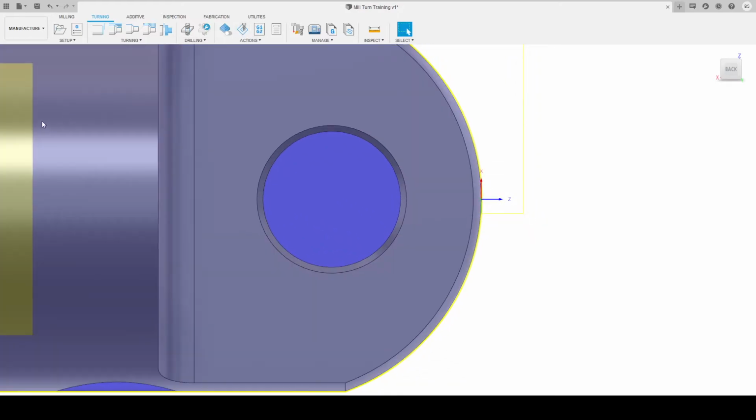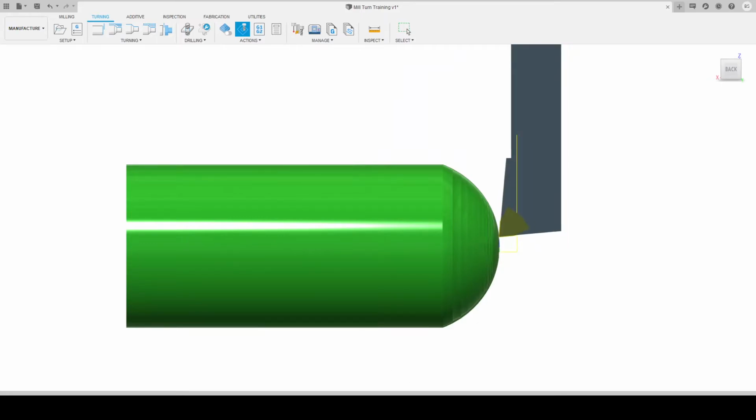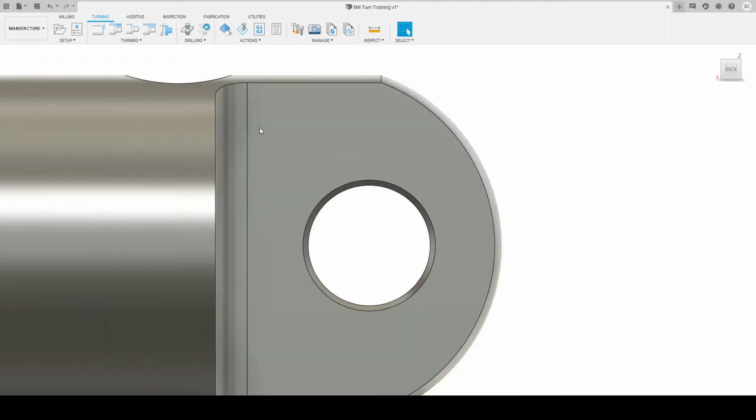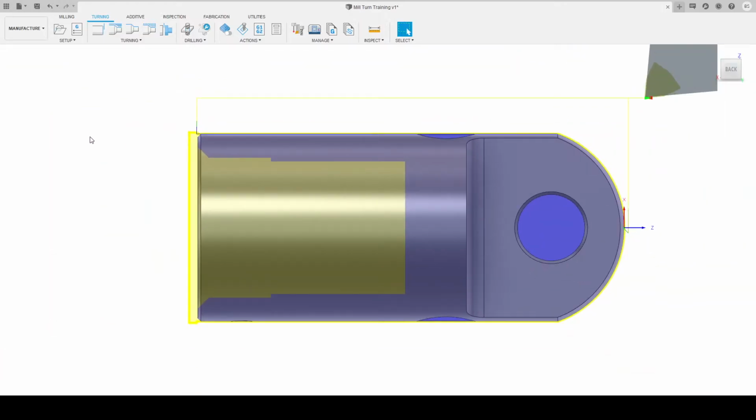So let's jump in and click our setup, and then simulate the whole lot. We'll jump forwards a bit, and slow it down a bit. Still doing it. It's because of our lead-in angle. So if we go 45 again, and then change it so the lead out is not the same, so lead out same as lead in, and then we can make that one 0. Now you'll see we actually get a lead in to this toolpath, and we should be fine.